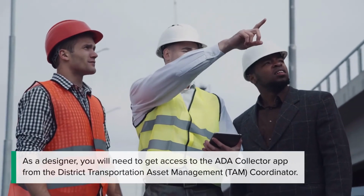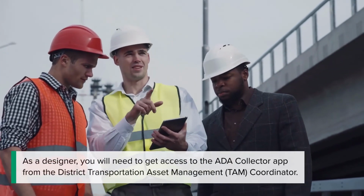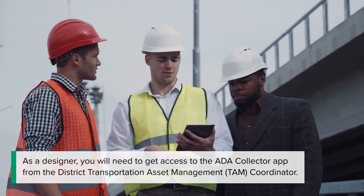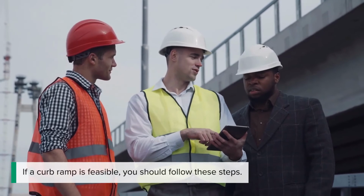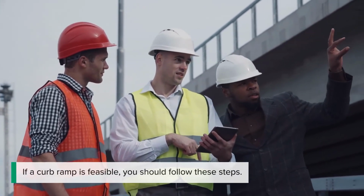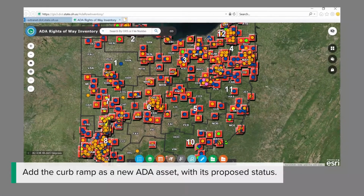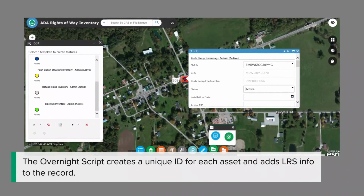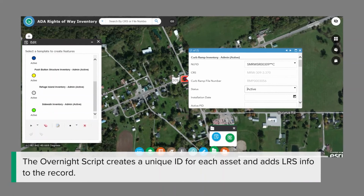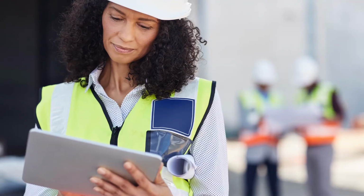As a designer, you will need to get access to the ADA Collector app from the District Transportation Asset Management Coordinator. If a curb ramp is feasible, you should follow these steps. Add the curb ramp as a new ADA asset with its proposed status. The overnight script creates a unique ID for each asset and adds LRS info to the record.